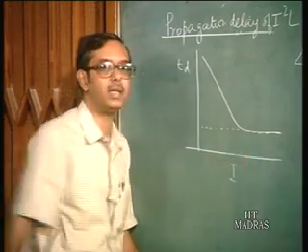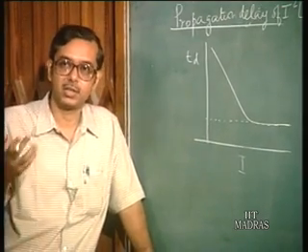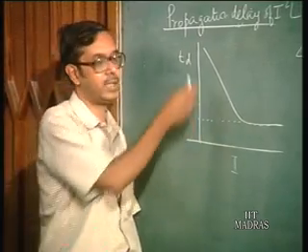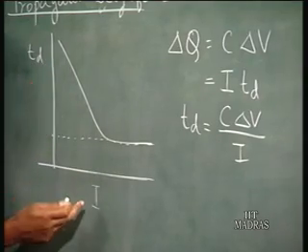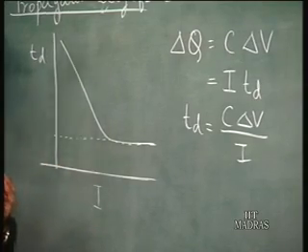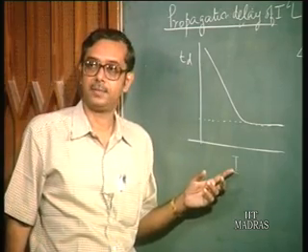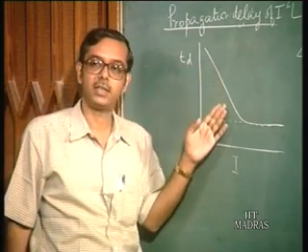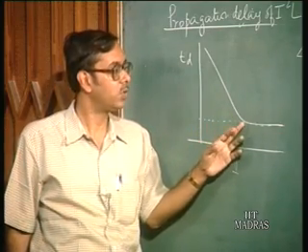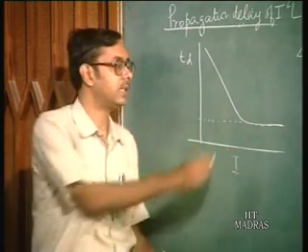So this is the minimum delay which you have, and it is determined by the diffusion capacitance or the stored charge effects in the device. Similarly, in an I squared L, if you plot the delay versus current, that is the total injector current or the current you are feeding through the power supply, and you increase that current, you will get initially a reduction in delay and then it saturates.